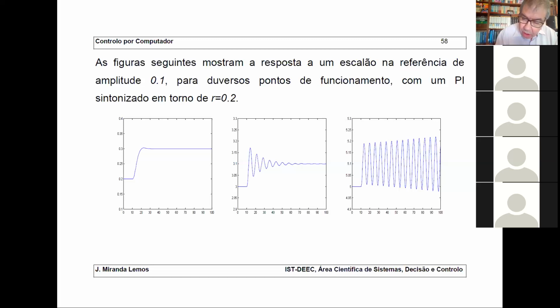So if you are adding too much air to the system, then the efficiency is low. But if you are adding too little air to the system, then you are just sending away unburned, unconsumed gas.